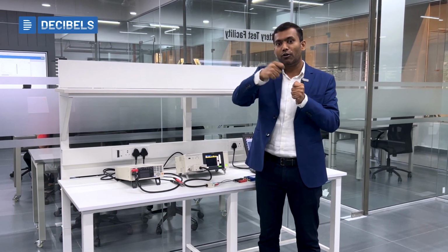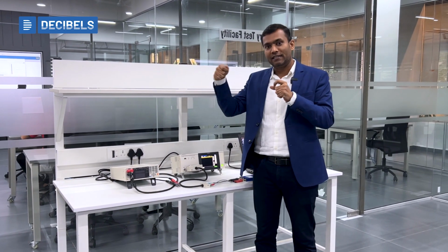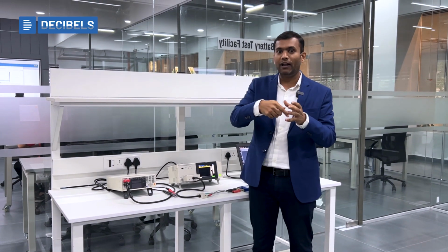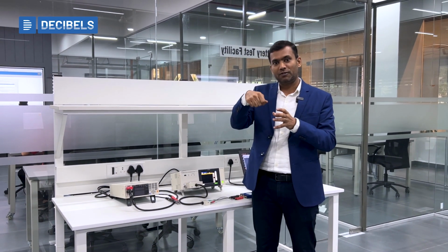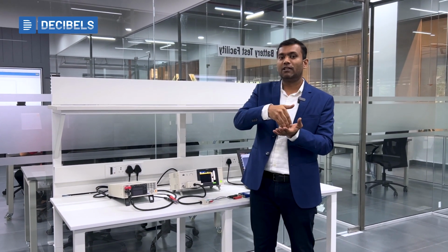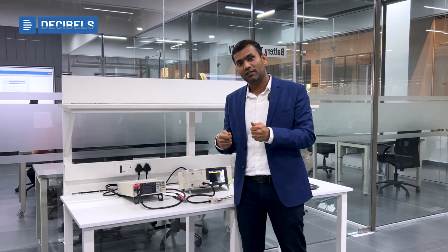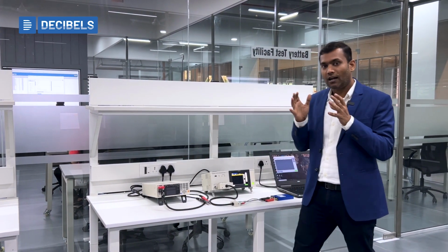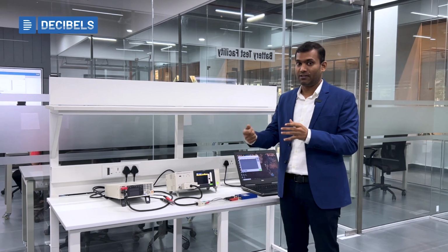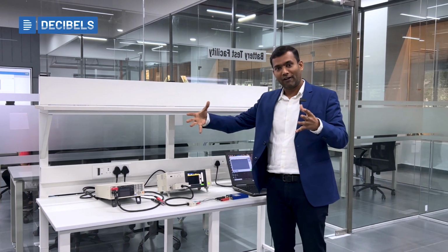Once the battery pack is manufactured, we have the contribution of different cells as internal resistance. Then we have our spot welding or manufacturing process for the bus bars interlinking the cells, the bus bar itself, and all the other components of the battery pack that contribute to the overall internal resistance. In such test cases, we use these machines to study the pack-level internal resistance. Imagine you have a battery pack manufacturing plant.